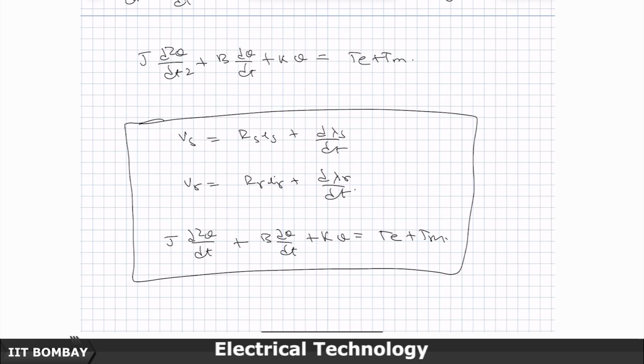But anyway, state space model we write when we want to study the dynamics of the electrical machines, but before doing the dynamics of the electrical machine we have to study the steady state analysis of the machine. In the steady state analysis, basically what happens, the rotor speed becomes constant. When you start your fan, it accelerates, then it comes to a speed and keeps rotating, that is the steady state analysis. When it is at 0 speed and until it has come to its steady state speed, that is the dynamic part of it.